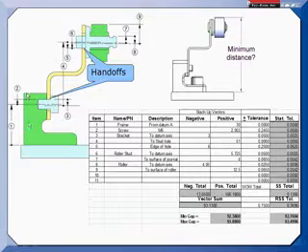If we start going through our vector analysis, we find that in this bracket we hand off from the screw to the bracket right here. So I would have a vector that goes to the datum plane of my bracket. Then I'd have a basic dimension, shown here as number 4, that gets me up to the center of the hole. And then I would have another vector that gets me to the handoff to the stud.